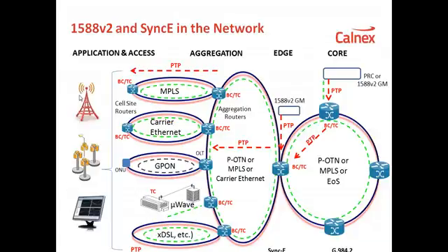Reason being, we need these sites to be frequency locked or synchronized, for example in the case of a mobile network, to enable calls to be made across the radio interface, and also to enable calls to be handed over between one cell and the next cell. So in order to synchronize this network, we need to transfer synchronization from a single source across a network.